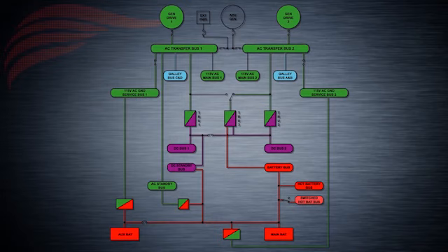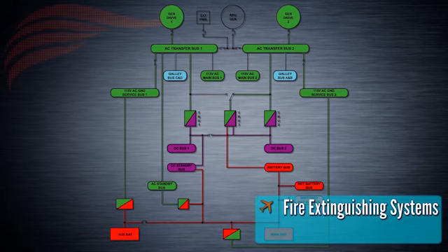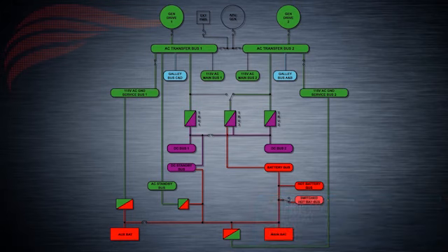Within DC power, there's also a hot battery bus. This DC bus is always powered and active and is in charge of maintaining energy for two main items: all the fire extinguishing systems and the captain's clock. The hot battery bus, similar to the battery bus, is powered by 28-volt DC power from the battery.